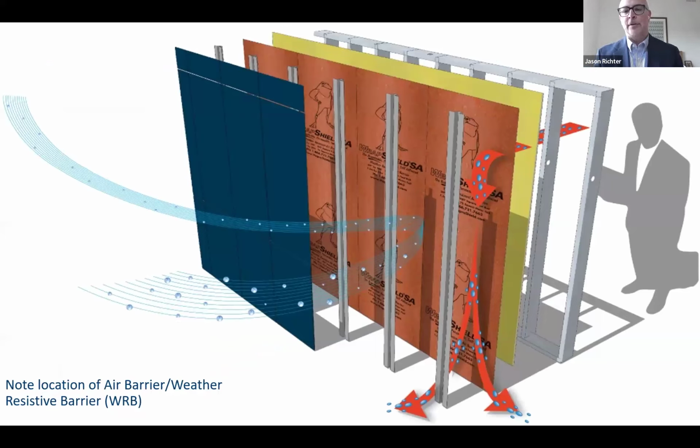So it will reject moisture coming through from the exterior, but it is now more often than not at least semi-permeable, if not fully permeable, allowing interior vapor to escape out. So again, we're pulling the moisture out of the building as well. So we need to make sure that we are allowing for that moisture to escape in the rain screen design.